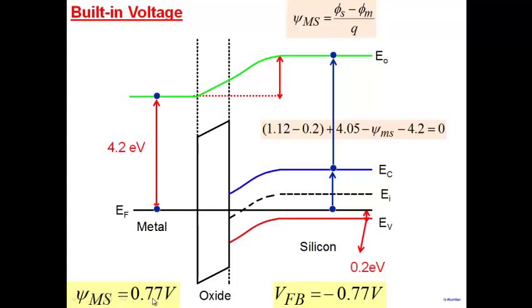All right. Note that this is the internal voltage which comes about because the metal has a work function which is different from the work function of the semiconductor. And as we said, anytime you place two different materials with different work functions, you will end up with a contact potential between them.